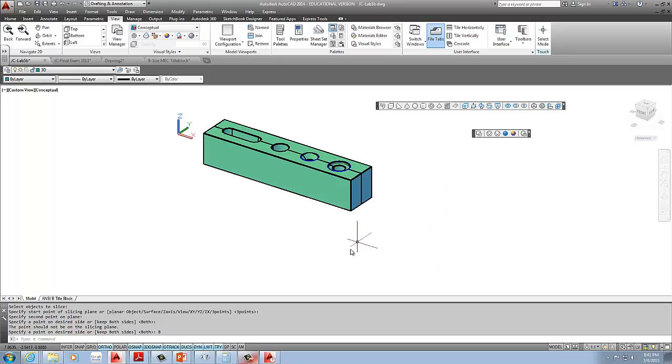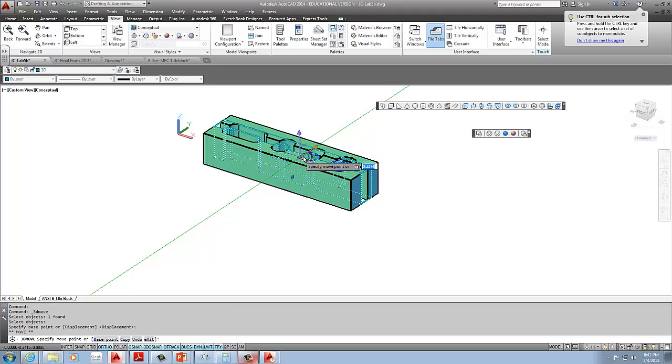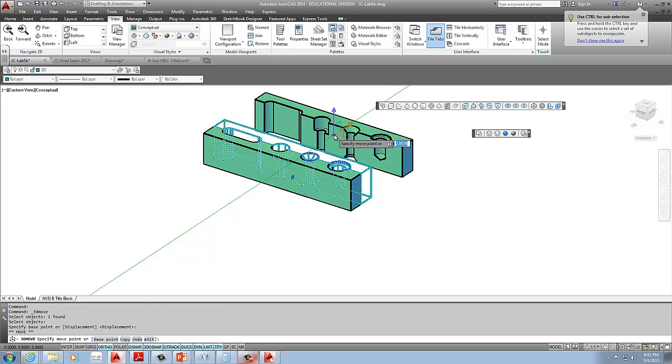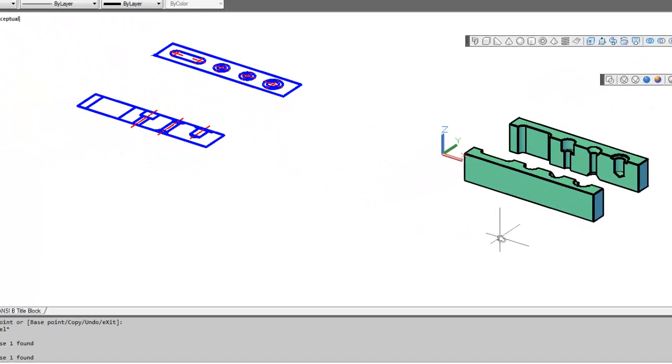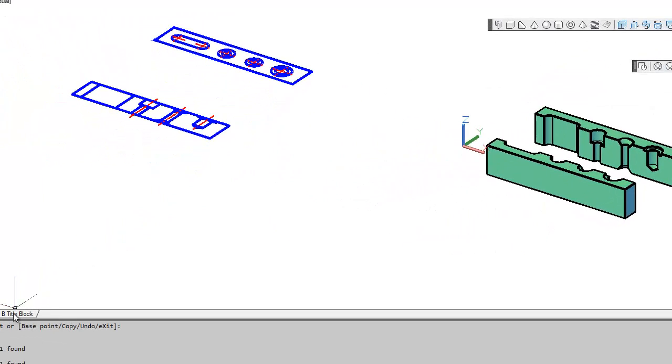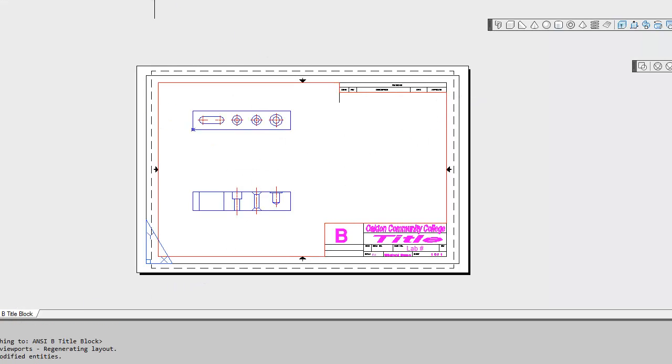And you'll see it slices it. Then I'll use a 3D move command to separate them and pull it by this rocket so that they kind of stay within the planes. I'll hit escape. I'll clean up my sketch geometry. And then I'll put that onto a title block by switching over here and then going to a viewport layer and creating a viewport.